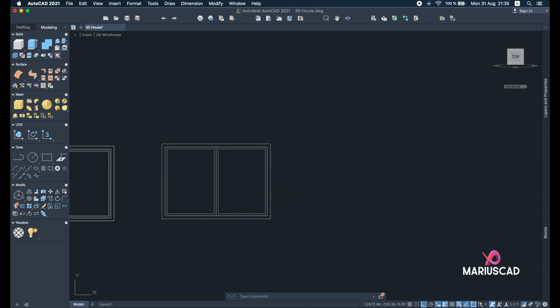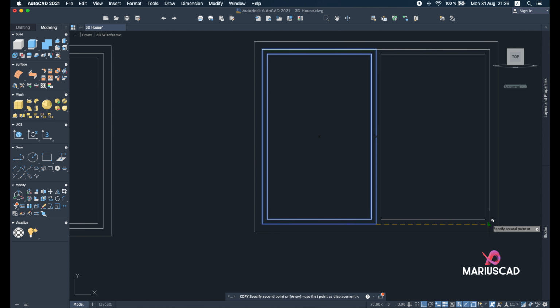The next window, so rectangle, 150, 120. Yes, offset now 5. Rectangle, from this point until you reach the middle, now you know the lesson, offset 3 units, that means 3 centimeters, I repeat. Select the 2 rectangles and go there.